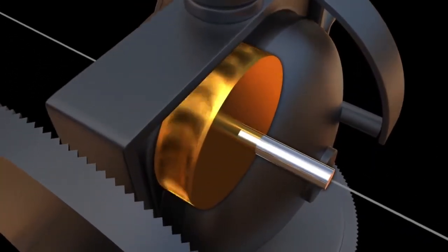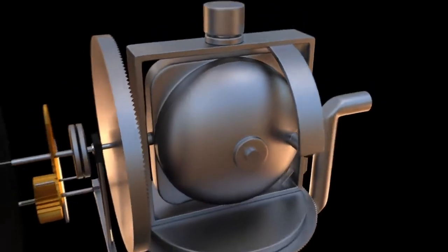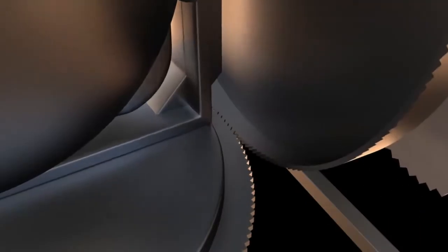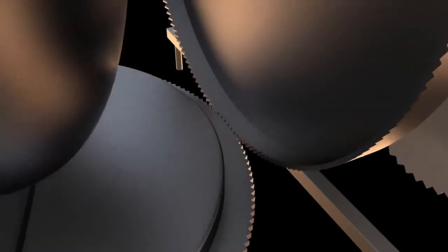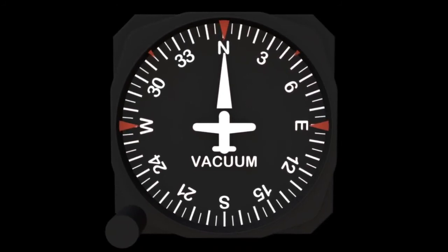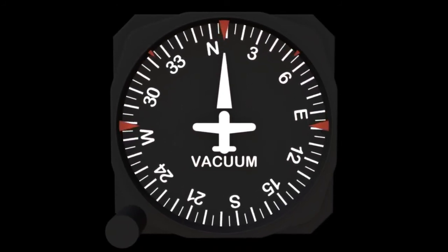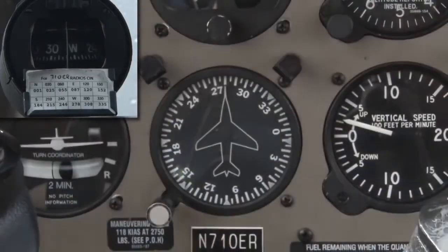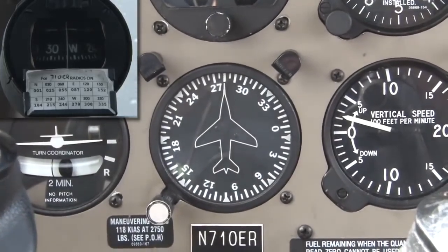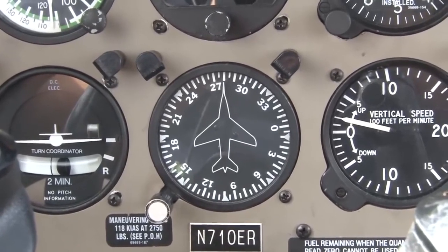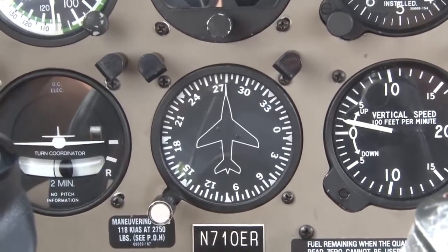Unlike the attitude indicator, the heading indicator is oriented so that only the horizontal axis is used to drive the display. When the aircraft turns, the gyro and attached main drive gear remain in their orientation, which causes the main drive gear to rotate the compass card on the face of the instrument. Due to friction and precession, the heading indicator may slowly drift away from the correct heading, and because of this, the pilot should double-check the accuracy of the instrument against the magnetic compass and realign it if necessary. This should be done roughly every 15 minutes.